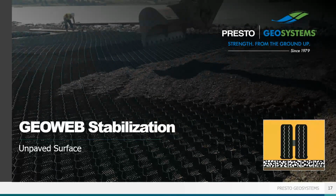Let's look at some examples from an unpaved load support system first. An aggregate surface has advantages in saving pavement costs, and with the GEOWEB system filled with open graded base course, you can design a system that allows stormwater infiltration and provides stormwater storage.